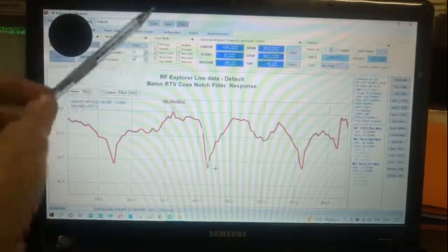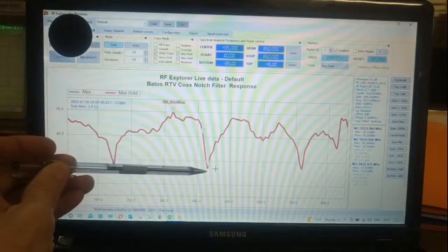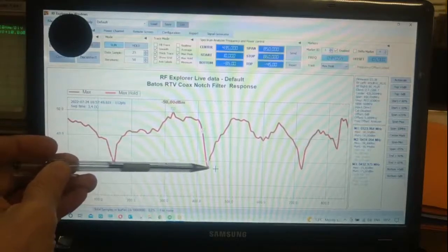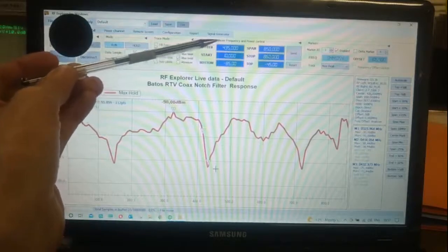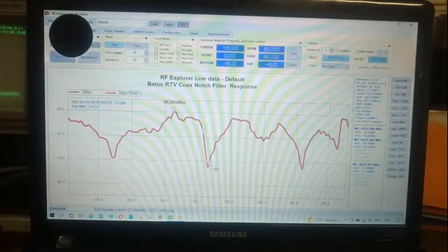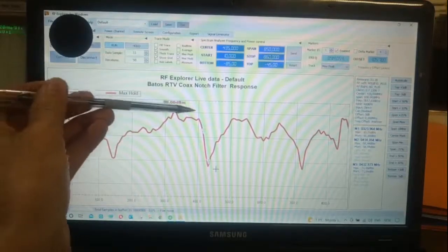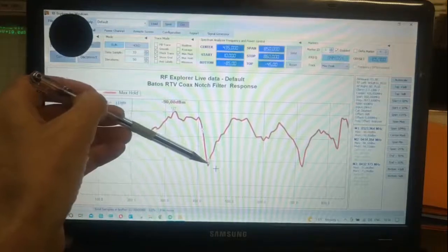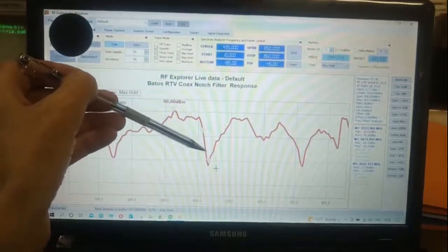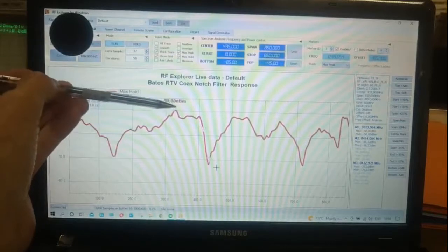And with this video, I've taken maybe my highest peak of the actual generator and compared it with the minimum peak, the lowest peak of the center frequency that I actually wanted, which is 435 megahertz, if you look at it over there. And that gives me, as I explained, something like 23 dB difference. And the 23 dB actually means that I have attenuated unwanted signals at 435 megahertz just over 200 times. That's what 23 dB translated in real time actually represents. This point over here is 200 times smaller than this particular point.